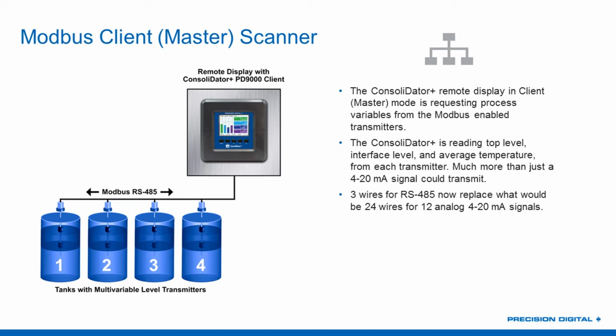And by the way, I want to mention right up front, these 3 modes are only for the RS-485 connection. Modbus TCP/IP is only for Modbus slave connections. So we can be a Modbus slave if you're going to connect to it over Ethernet. But if you're using RS-485, that's where you get access to all these other features when you get that Enhanced Features package.